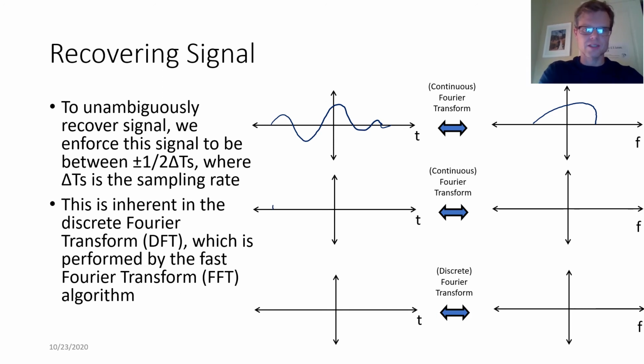Now when we digitize this signal, with some sampling interval, I'll do my best here to draw this, and we can label we have some time sampling interval here. What I just said is that we're going to get replicas of our original Fourier transform at these integer multiples of 1 over delta TS.